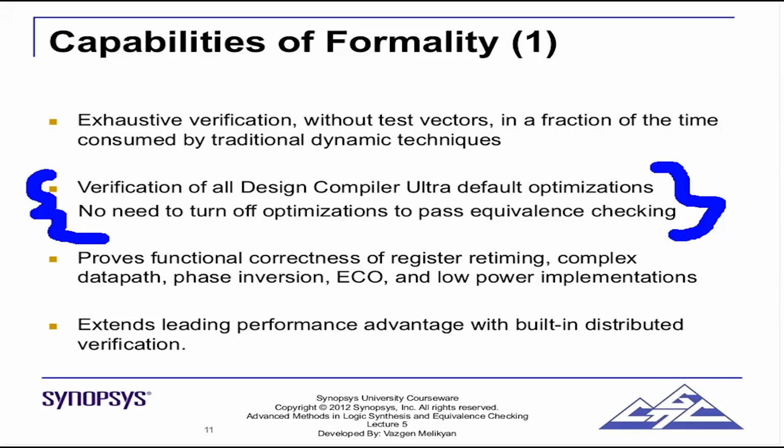We saw an example in the detailed representation that the flops are placed at logical boundaries in RTL. But let's say we have violations in synthesis, then DC can move these flops around for you to borrow some timing slack from the next or the earlier stage which has positive slack. Now the problem with retiming is that although at the port level the designs are functionally equivalent, if you consider flops, the flop in the RTL is now not equivalent to the retimed flop in the netlist.